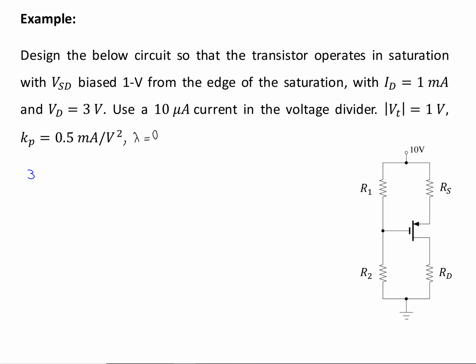The first one, I have 3 times R1 plus 3 times R2 equals 10 times R2. From there, I have 3 times R1 minus 7 times R2 is equal to 0. From the other one, R1 plus R2 is equal to 1. I know that the resistor values that I'm going to get from these two equations have the unit of mega ohm, because the current that was flowing through R1 and R2 was in the range of microamp.